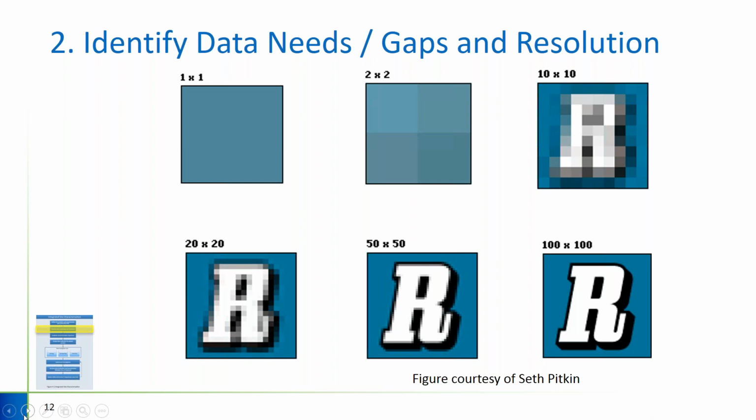But that is a factor of 4 higher resolution than the one next to it. So what if the cost goes up by that same factor? What if it's linear? So is it worth 4 times the cost to go from the 50 by 50 to 100 by 100? Well, maybe not. Maybe the 20 by 20 is good enough, depending on what you're trying to do. And so the point is you try to find the best sort of mesh point of cost and the resolution.